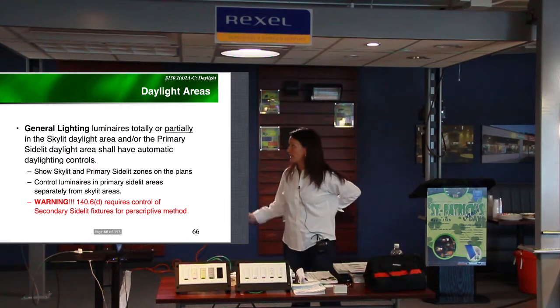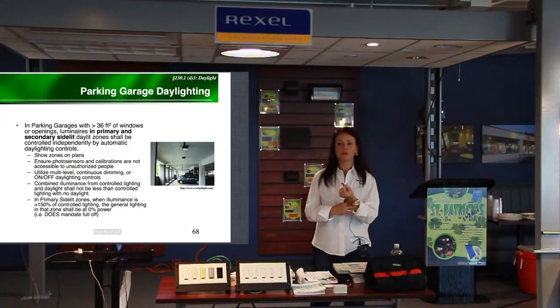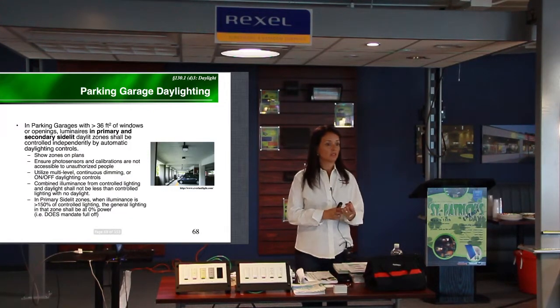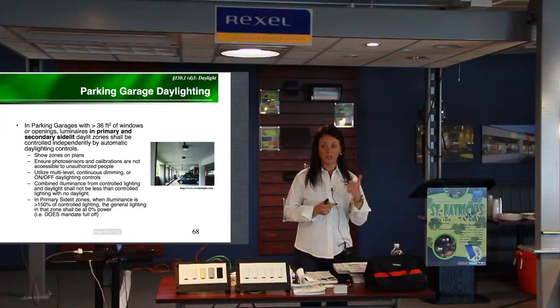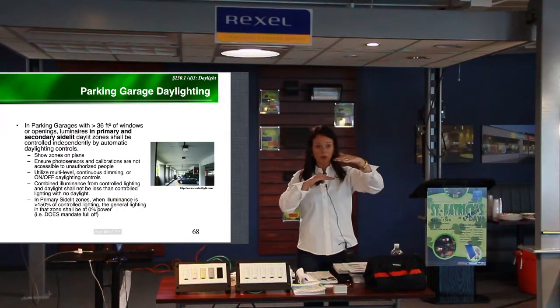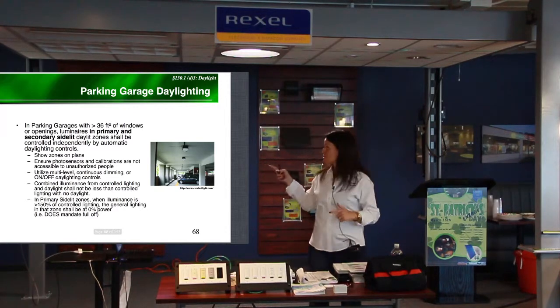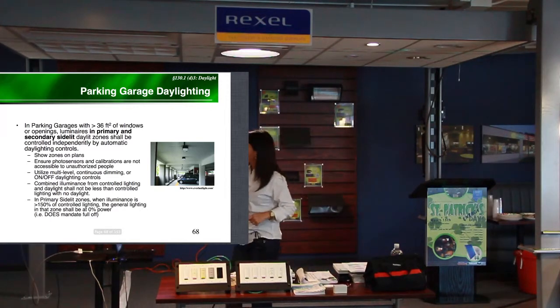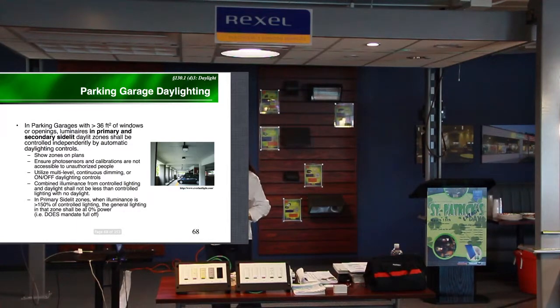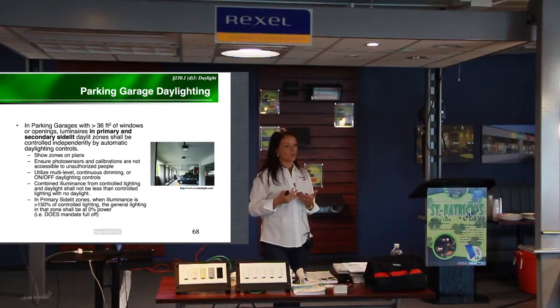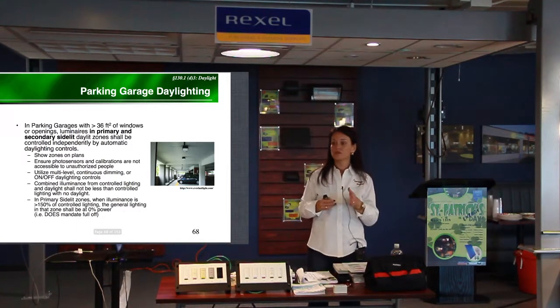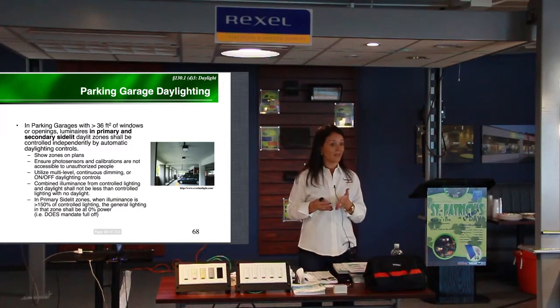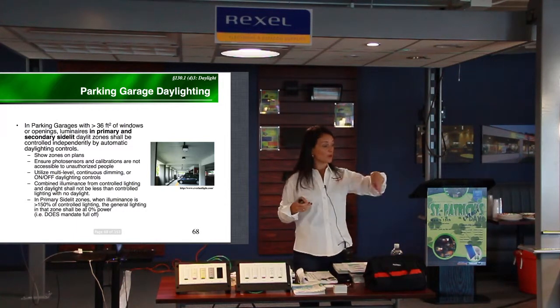Parking garage daylighting, I mentioned that parking garages now need to follow the high-low level without automatic shut-off, except in those fixtures within the perimeter if there's some daylighting contribution. So you need to provide some automatic daylighting control for those areas in the perimeter of the parking garages.